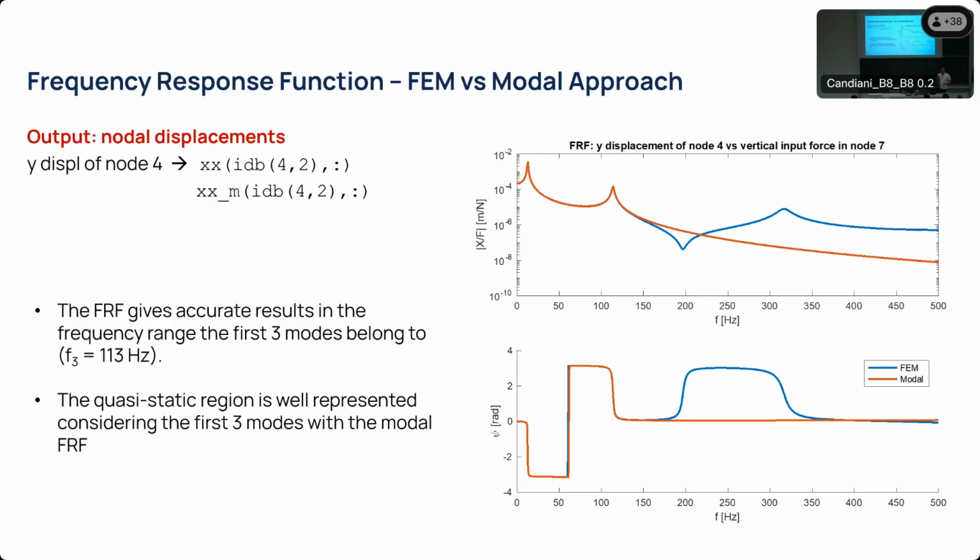If you want an analogy, you can look at it like a Fourier transform. If you remember, the Fourier transform was a way of expressing the displacement time function as a sum of sines and cosines at increasing frequency. Usually, with an ideal discrete Fourier transform, you can completely reconstruct the signal. But if you cut at a certain frequency, if you filter out all the frequencies higher than your threshold, you will lose that frequency contribution in your reconstruction, and so you will have a partial, filtered signal out of your inverse Fourier transform. In this case, we are using not the same approach, but with mode shapes.